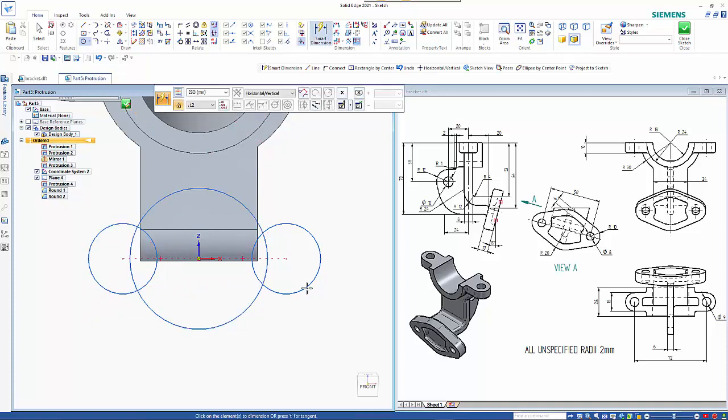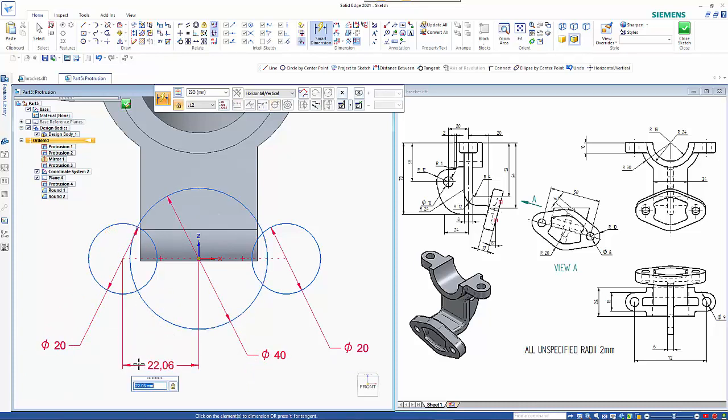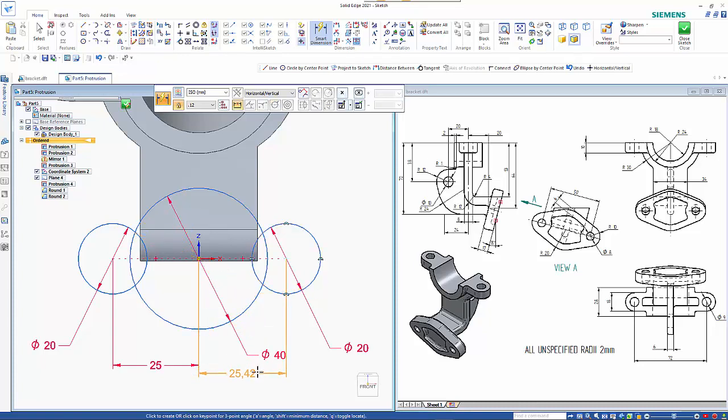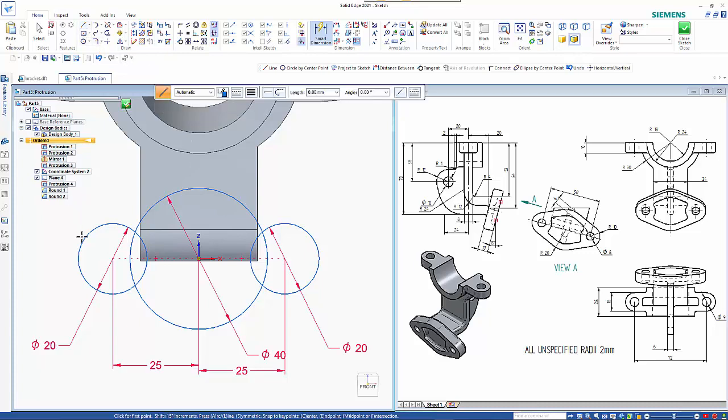So then I can have my dimensions, and by drawing to size we're obviously cutting out some of the resizing or positioning. So then we're just drawing our tangent arcs, or tangent lines, sorry. Making sure that I'm getting my tangency symbol on the second arc.